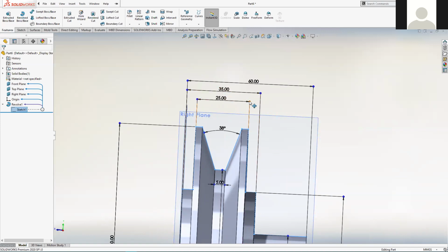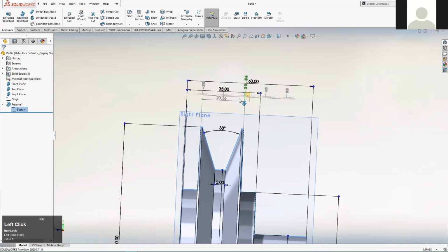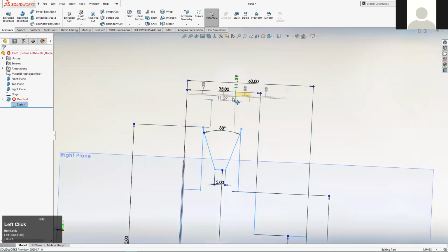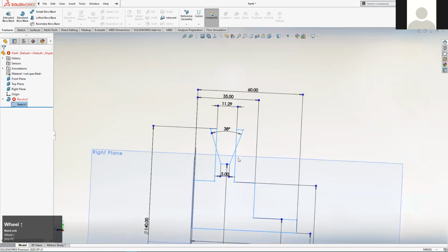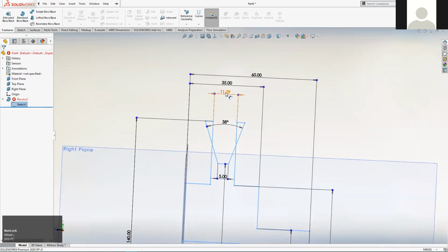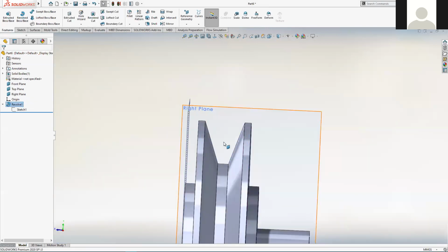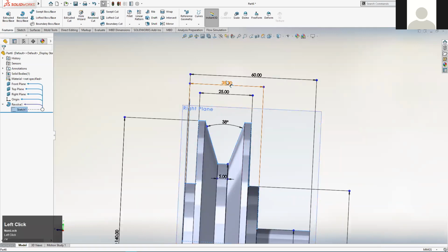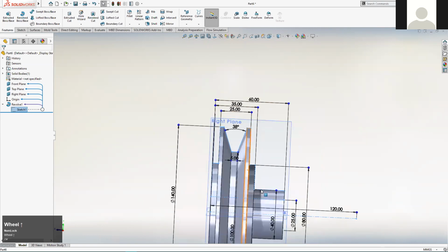There are certain scenarios where the sketch is going to collapse. So there you go. I've made the sketch collapse in on itself. So you've got to be a little bit aware of that as you're doing work on such a complicated sketch, that there are certain combinations of values in this sketch that will cause this profile to not work anymore.